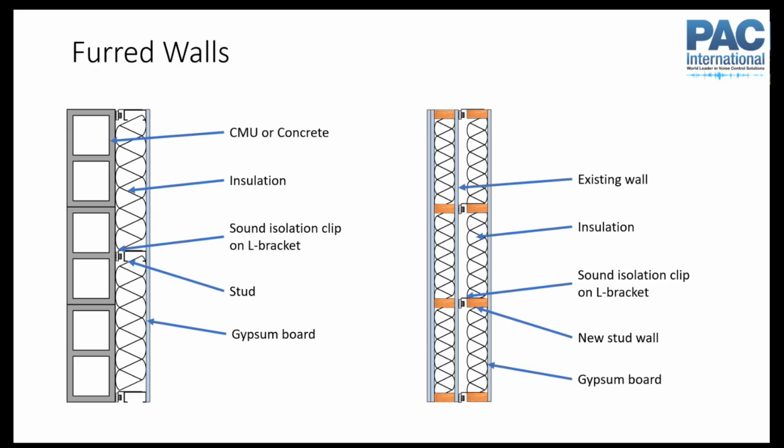And also, you just want something other than a CMU finish for your wall in your apartment, right? So we'll frame out some other kind of wall, but maybe we need to tie back to that CMU block wall because that's a structural wall. We need to tie back to it, just support it so we can use lighter gauge studs, thinner studs, these kinds of things. So we can use an acoustically isolated L bracket. It's got a little rubber isolator in it to tie those studs to the CMU block.